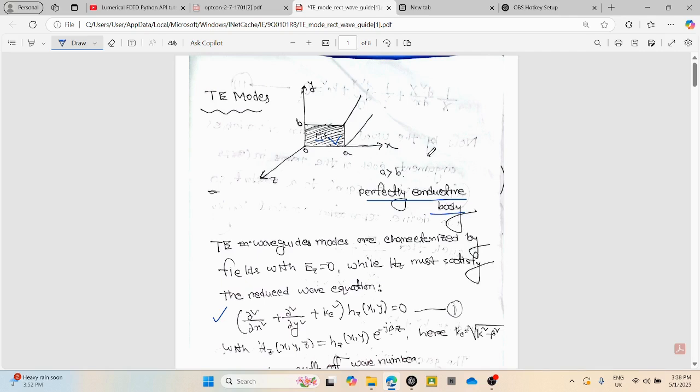Rectangular waveguide. Rectangular waveguides are one of the earliest types of transmission lines used to transport microwave signals, and they are still used for many applications. A large variety of components such as couplers, detectors, isolators, attenuators, and slotted lines are commercially available for various standard waveguide bands from 1 to 220 GHz.